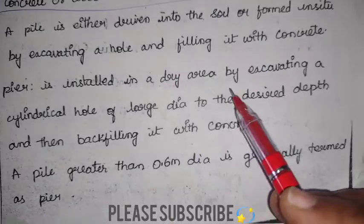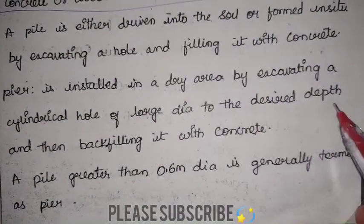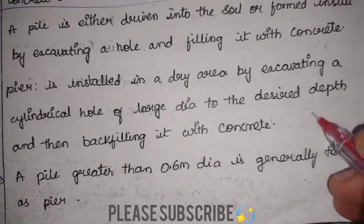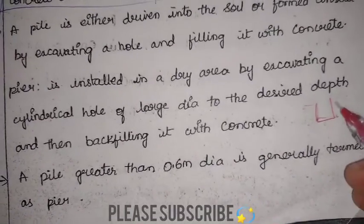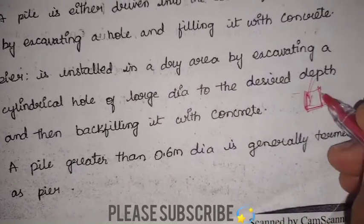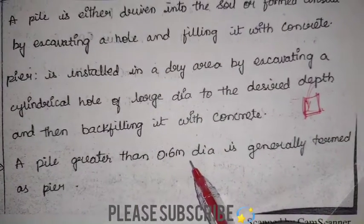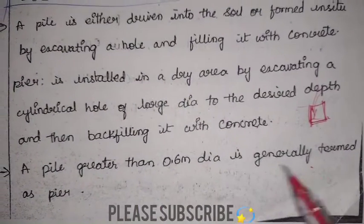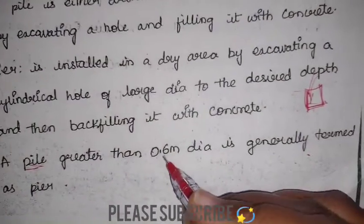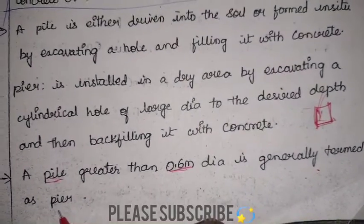So here we have pier. It is installed in a dry area by excavating a cylindrical hole of larger diameter to decide the depth and then backfilling it with concrete. So here first of all we are just digging a hole, and to this hole we are filling in concrete. This is the foundation that is formed. A pile greater than 0.6 meters diameter is generally termed as pier. Whenever a pile which is greater than 0.6 meters is formed, we are terming it as pier.